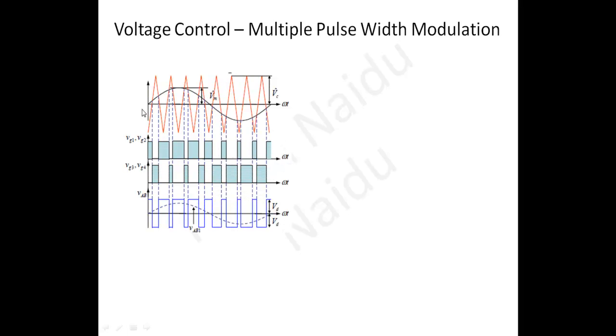If you go for a sine wave like this, you can see that we are getting pulses, but the width between the pulses is different and the width of the pulses is also different. Generally, the pulse width will start very small from the starting, and then while going towards the maximum you will get a bigger pulse.